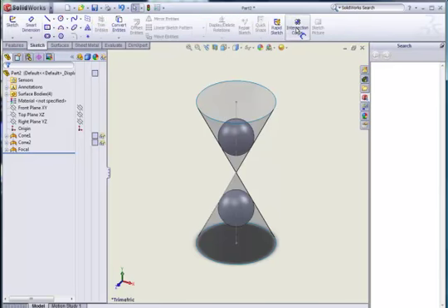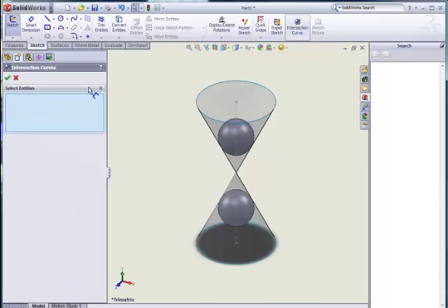So if we press intersection curve, and we want to select the bodies that will be intersecting, so select entities will be both of our double cones and both of our focal spheres. And if we press OK, this generates a 3D sketch, in this case being our circles of contact.